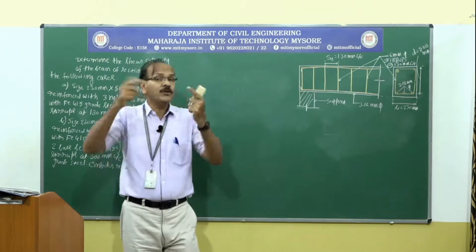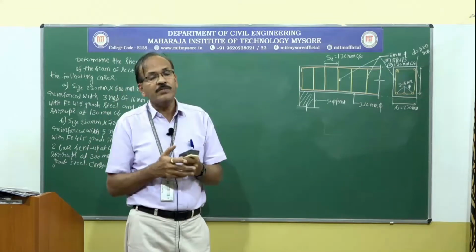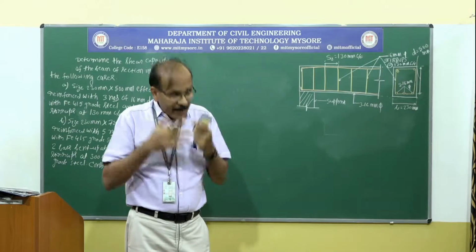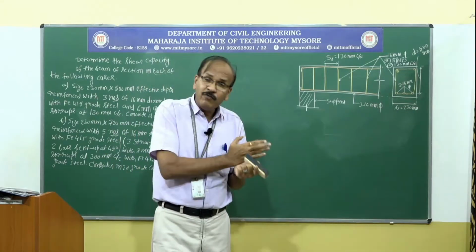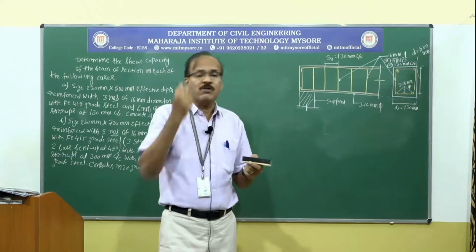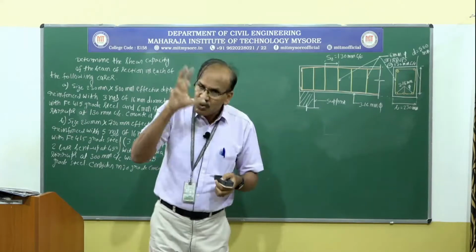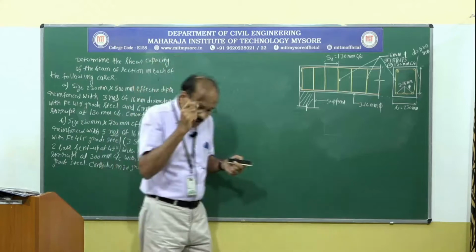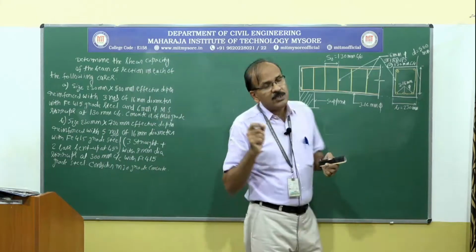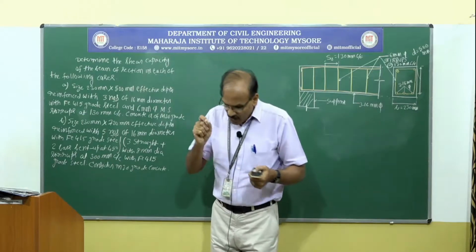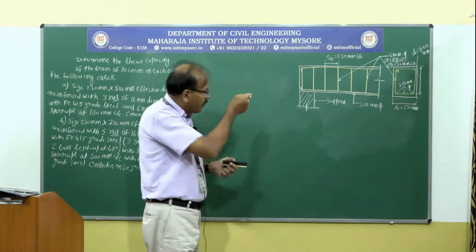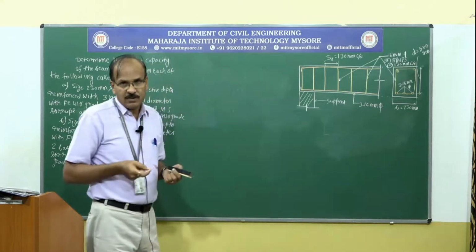So, total shear due to the external load coming on that beam will be carried by the reinforcement and by the concrete. When it comes to the concrete, the shear capacity of the concrete depends on the percentage of reinforcement. And once we start solving the problem, I am going to explain in detail what it is.